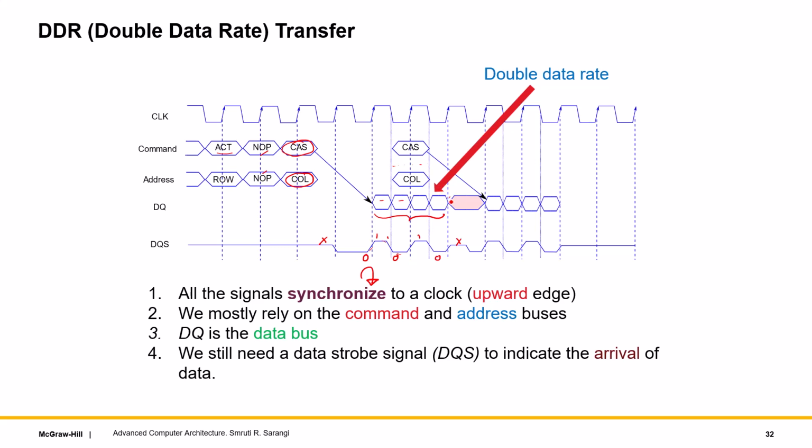And then the point is that after data is transferred, we are giving some time for the bus to restabilize and recover. After transmitting 2 of these bits, we are sending a column address strobe once again. For this to take effect, it will take some time.